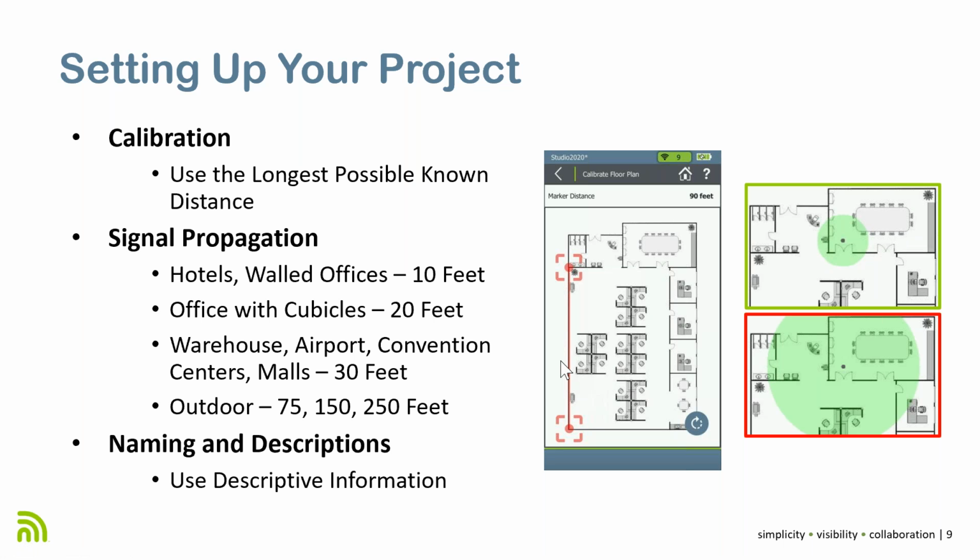A good tip or best practice for any site surveyor is to always carry a measurement tool with you. If you have one of those little laser measurement tools, make sure you keep one around so you can take accurate distance measurements for your calibration.